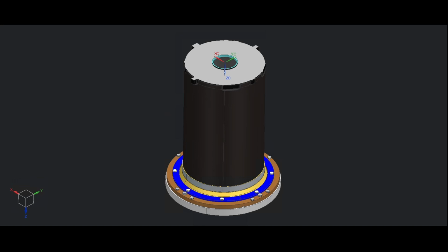We are going to focus on the bolts used to mount the optical payload to the shaker table. These bolts must be verified to ensure that they will not fail during the test, thus causing damage to the component being tested. The verification consists of determining the margins of safety, which depend on the bolt size and material, the number of bolts included in the mechanical system, and the load experienced by each bolt. And the breakdown of the model is as follows.